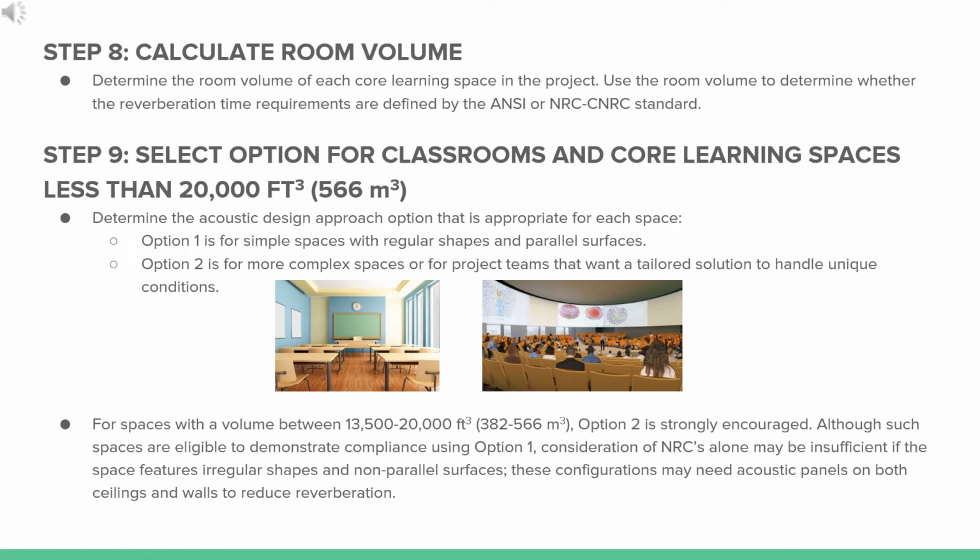Step 8. Calculate room volume. Determine the room volume for each core learning space in the project. Use the room volume to determine whether the reverberation time requirements are defined by the ANSI or NRC-CNRC standard. If the space is less than 20,000 cubic feet, proceed to Step 9.